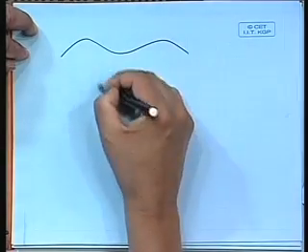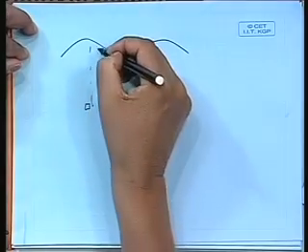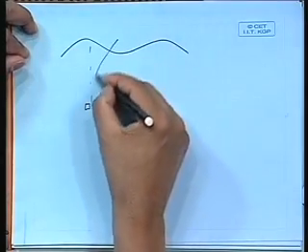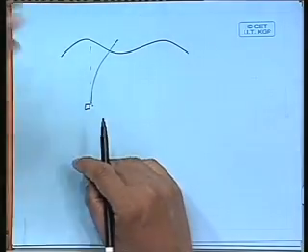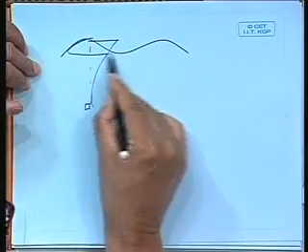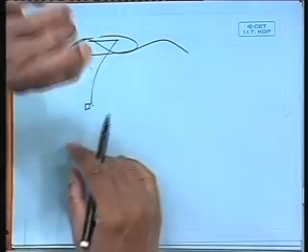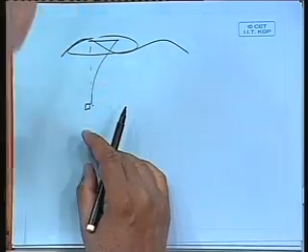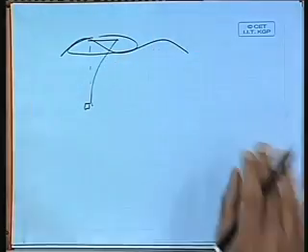In other words, when you go down about half the wavelength, everything comes down. At some point here, you will not even feel there is a wave there, because everything decays exponentially. This is exactly why if there is a storm up, and you are diving down, you won't feel there is a storm up. And the second thing is that everything happens in this area most, because the largest velocities are concentrated near the surface. Unfortunately, ships float at the surface. If it is a submarine, all you have to do is just dive down. There is a big storm, let it go on the surface. Simply dive down, go a little deep, nothing will happen. You won't even feel water is moving. This is an important characteristic, one way to see.